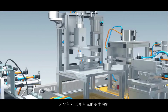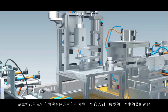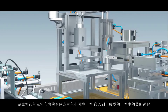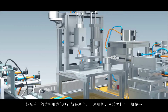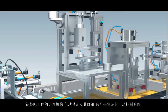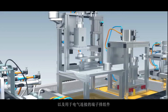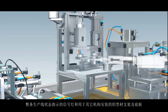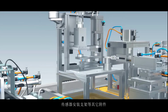Basic function of assembly unit: to complete the assembly process of the black or white cylindrical workpiece in the silo into the finished workpiece. The structure of the assembly unit consists of a simple silo, the material body, the rotary material table, and the manipulator, the position mechanism, pneumatic system and valve group, signal acquisition and automatic control system of the assembly work, and the terminals for electrical connections. The whole production line status indicator signal lamp, and the aluminum profile bracket and floor for other installation, sensor mounting bracket and other accessories.